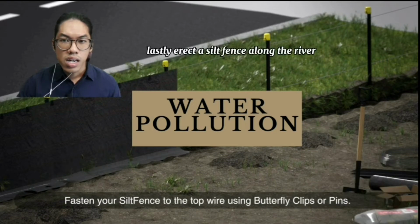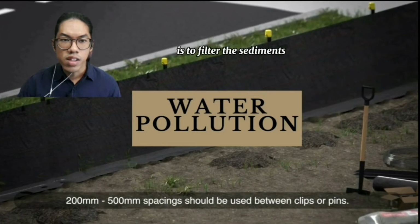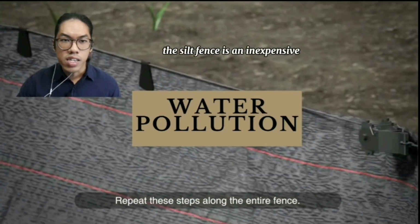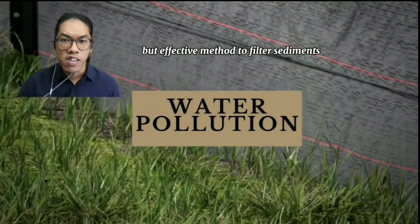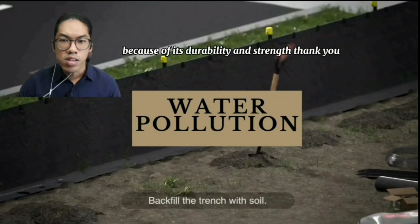Lastly, erect a silt fence along the river. The purpose of the silt fence is to filter the sediments but allow the water to pass through it. A silt fence is an inexpensive but effective method to filter sediments, and it is also reusable because of its durability and strength.